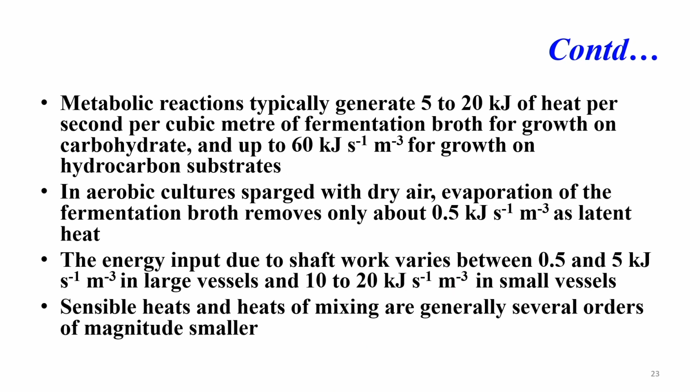So, what we can see here, in the case of metabolic reaction, they generate 5 to 20 kilojoule of heat per second per meter cube of fermentation broth if the substrate is carbohydrate, and if you change the substrate to hydrocarbon, this energy increases up to 60 kilojoule per second. In anaerobic culture, when you sparge with dry air, there may be evaporation loss and it removes about 0.5 kilojoule per second as latent heat.